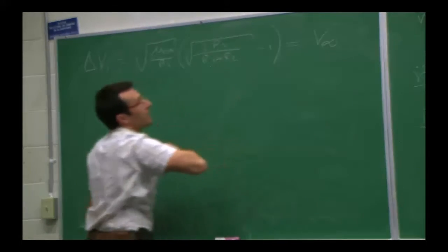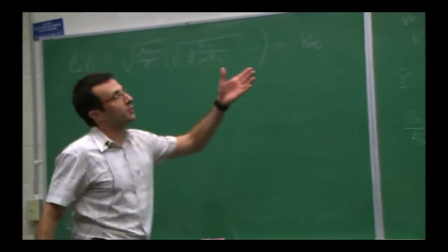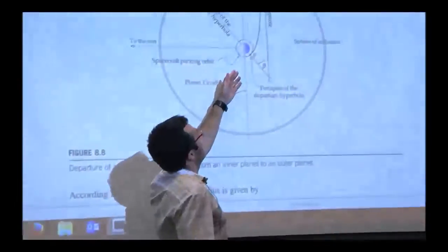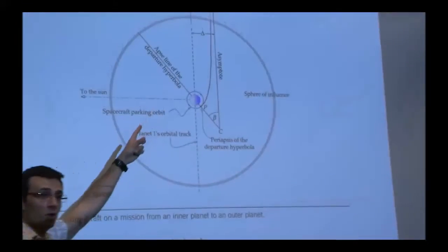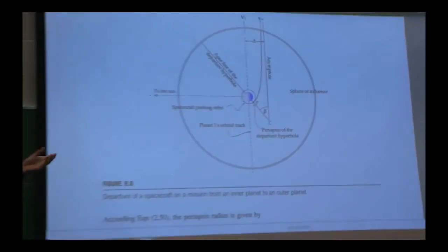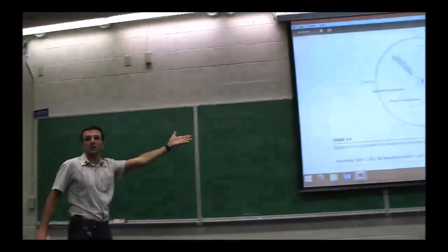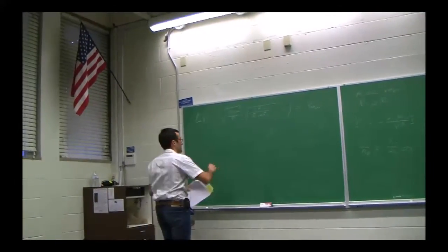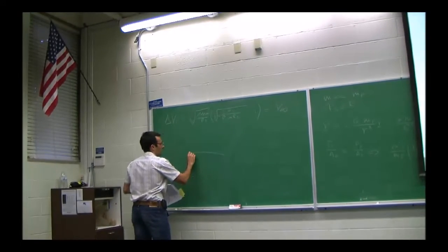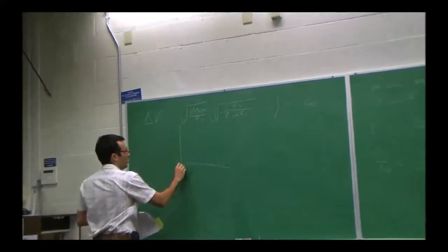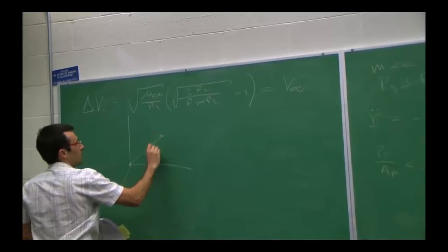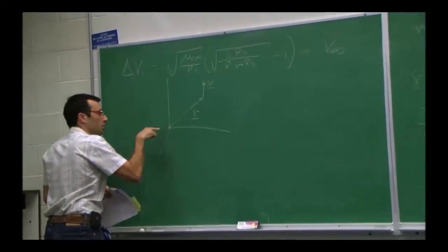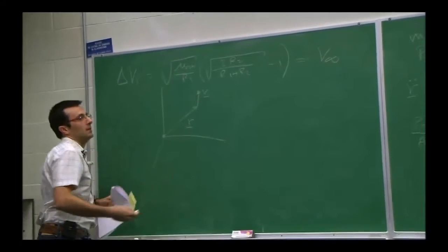Because with respect to the sun, if you're going on a hyperbolic trajectory, you are going to fly at a velocity which is V of your home planet, V1, plus the velocity relative to the planet, V infinity. Right? Everything that we have done up to this point, remember in the ECI, if we're talking about Earth-centered orbits, everything we have done where we talked about these little R vectors and V vectors, these are all relative to the planet. The planet is going around the sun.